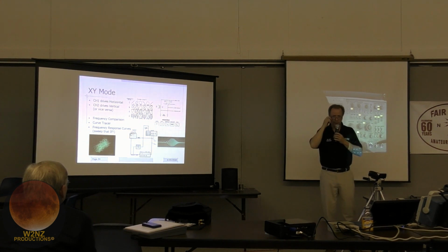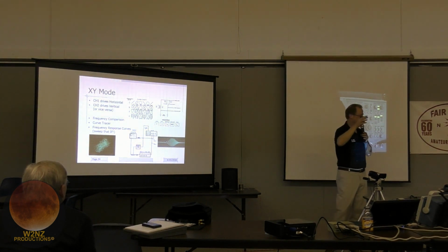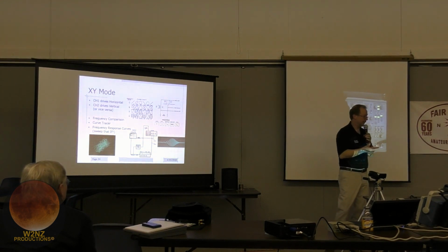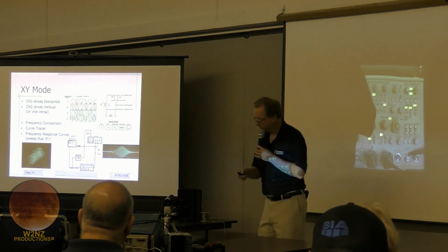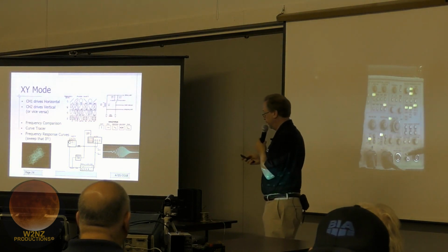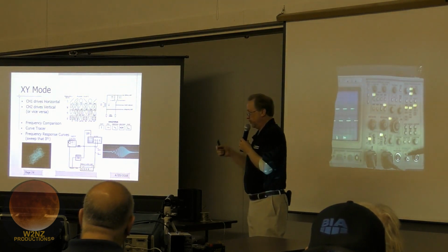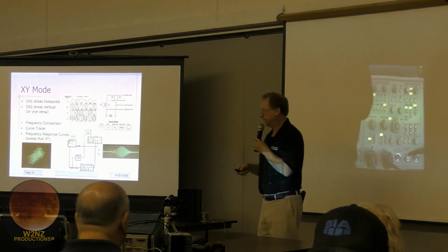If anybody's ever used an old Huntron tracker for testing, working in a TV shop or something like that, that's what they did. Basically, the Huntron tracker was a fancy octopus tester. I did a video on that. You can go make your own. What it's useful for is just a quick check on components.